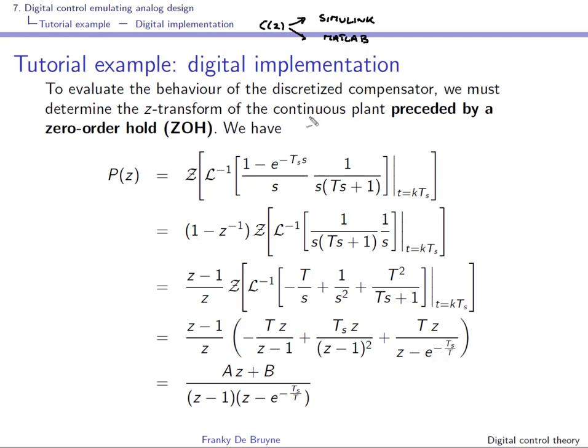and then you'll need a description of the system that will be including the zero order hold mechanism. So you'll be able to simulate the system at the sampling instants, but what you will not have is the inter-sample behavior. We are now looking for the zero order hold equivalent description of our system.